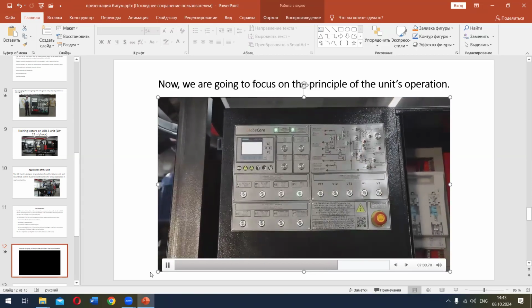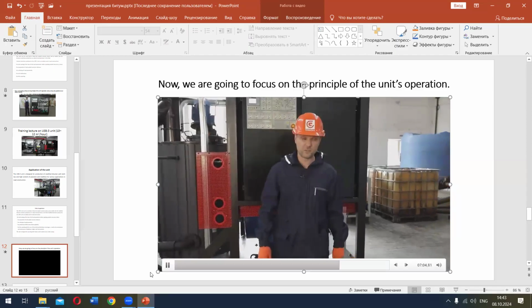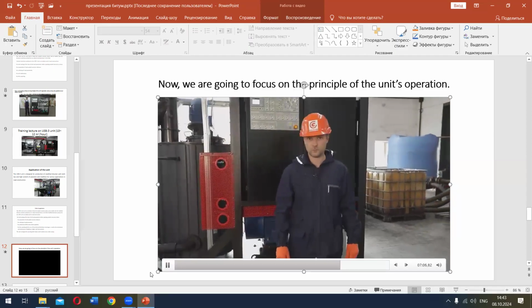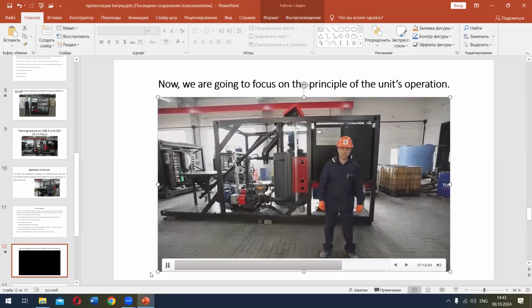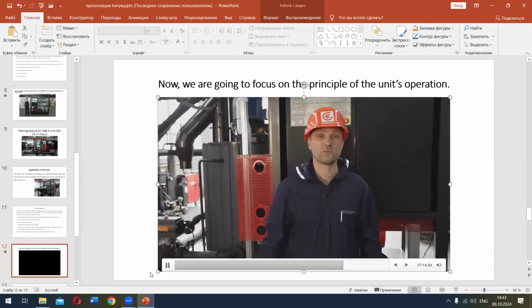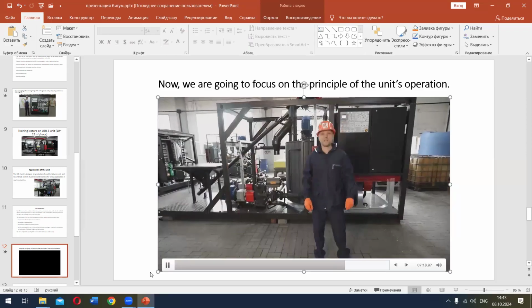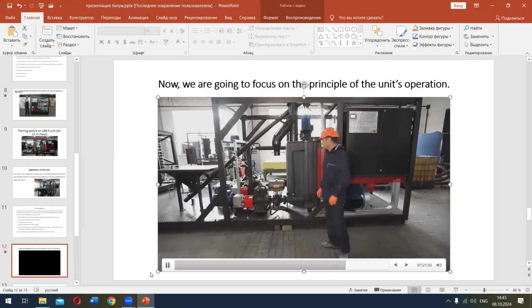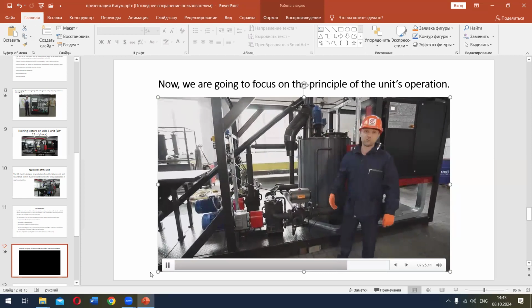After the operator enters the calibration results, the unit can operate in the automatic modification mode for as long as desired. It should be noted that calibration of ingredients is a fairly simple process which normally takes not longer than one work shift. Recalibration may only be required due to replacement of utilized ingredients. Actually, all assemblies of the unit are equipped with frequency converters, which makes it possible to vary the modified bitumen formulation over the widest range.